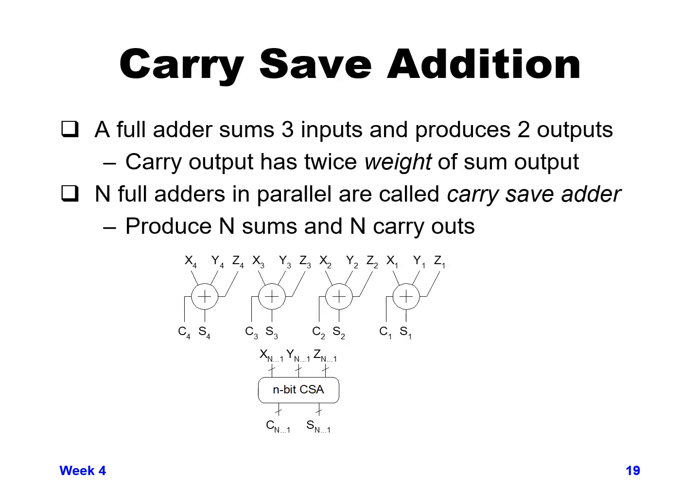So one thing that we can note in making an adder that adds more than 2 numbers is, if we go back to the full adder design for each bit that we had at the very beginning, we talked about how we have a value of A, a value of B, and a value of C in coming in. So we have 3 inputs to each bit of our full adder and 2 outputs come out. We have the sum value and we have the carry value.